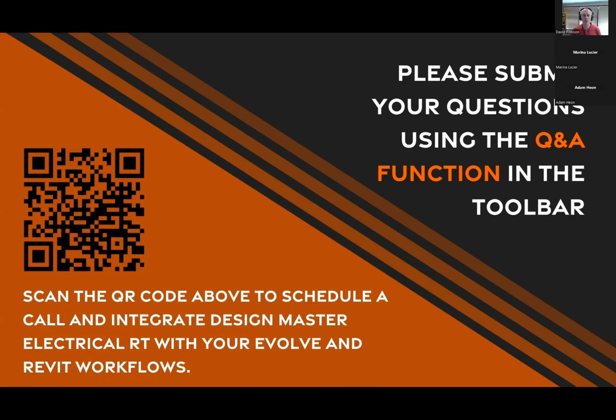But the basic idea is that we're using the positions of the devices in Revit to calculate those lengths. So if we take a look at this LP1A, we use the location of the upstream panel MDP1, and then how you're specifying you want that length calculated, either right angles or straight line. And then we have the wire length makeup. So the panel's down here. So right angles is going to be this way, and then this way. Excuse me, the straight line is a straight line between the two, and then any elevation change.